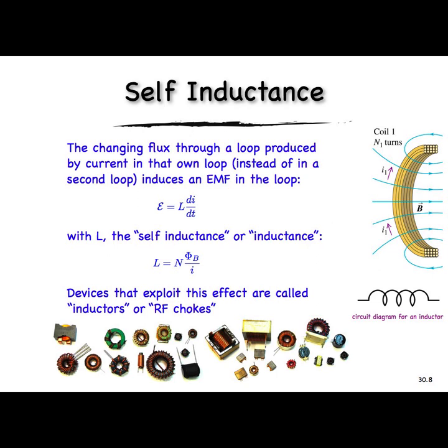Right, there it is. dI/dt I can figure out. I can take the time derivative. Time derivative of a cosine is a sinusoid. So I get minus sine, and then I bring the argument out. Right, take the derivative of the argument, I get an omega. So I'll plug in this term down here. This minus sign and that minus sign cancel. I get plus. And I get an expression for the EMF in coil 2. Because my current is varying, now I have an EMF in coil 2.